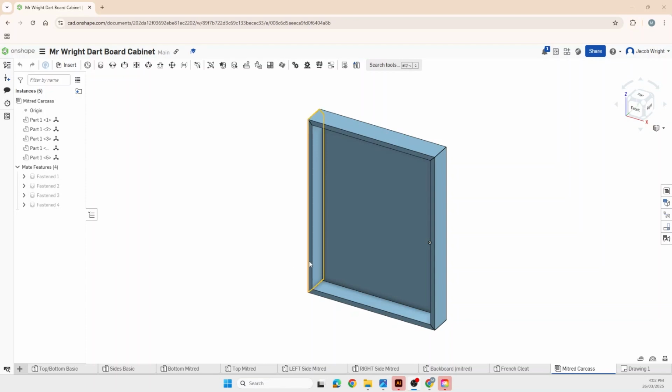So I'm going to be adding a shelf that runs directly across the bottom here, about 100 millimeters up. I'm also going to add a little divider in that shelf to divide the shelf, or this little area down the bottom, into two separate parts. So we're just going to do that to start with using housing joints. Okay, so as you can see on these parts, each of them already has a groove to house the backboard. Okay, so I know exactly where the backboard's going to sit, so I can draw my housing directly into it.